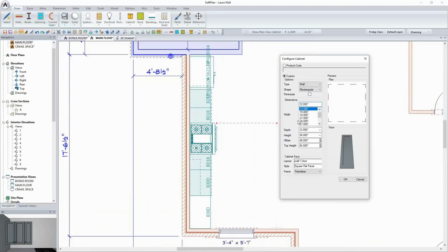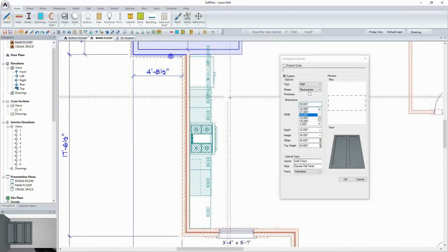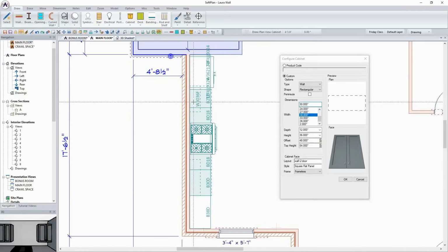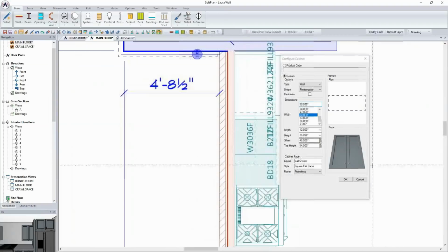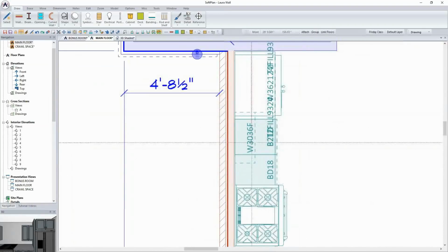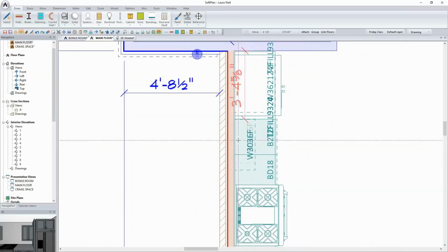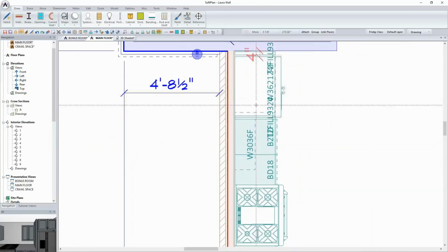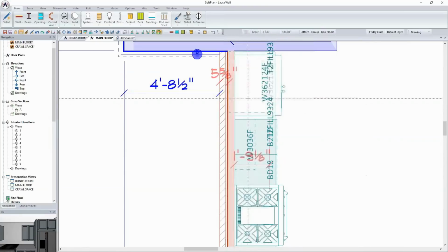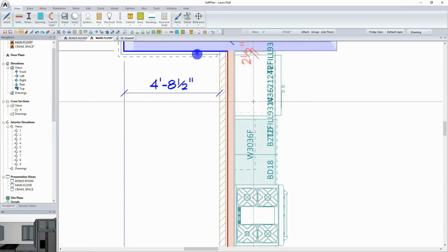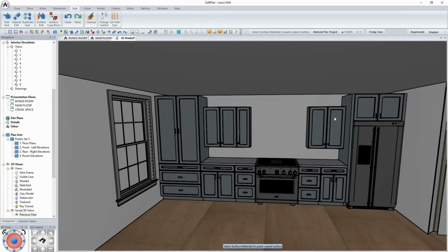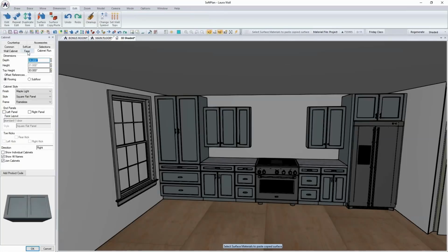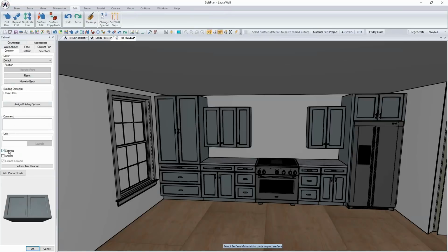And so again, over on this side, maybe not quite the same symmetry. I may just pick the 30-inch and add it only to this side right here, and it's snapped to, in this case, my wall cabinet. So I'm just going to manually move this cabinet to the other side of the filler. If you do have to move any cabinets, because what's happening here is just the cleanup feature finding a wall, you can always simply edit a cabinet itself, go into the common tab, and remove it from cleanup so that it holds its position.